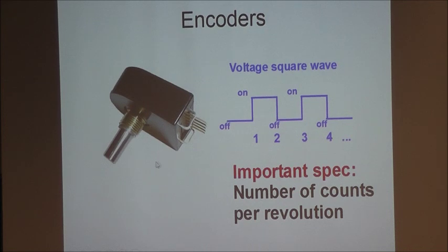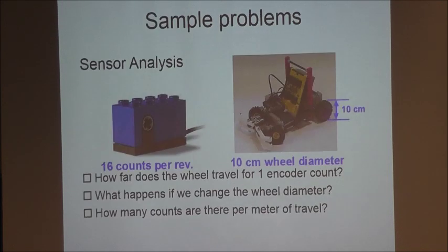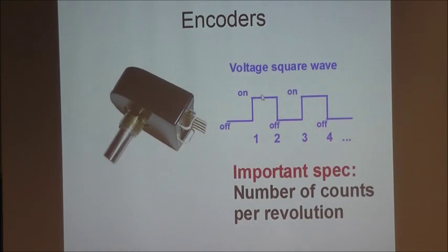What it does is it actually has a light source which goes from one side of the encoder, and the encoder is rotating with the speed of the motor. Depending on the frequency and the speed of the shaft of the motor, this particular device lets the light go through, and then you can see what part is on and what part is off. Okay, and I'll get more to it later on. I have more slides on this.